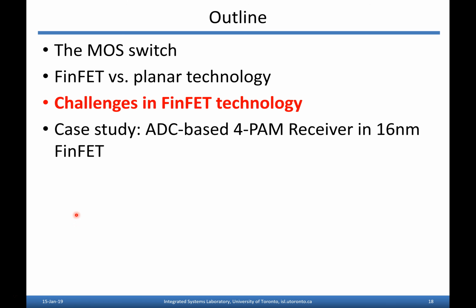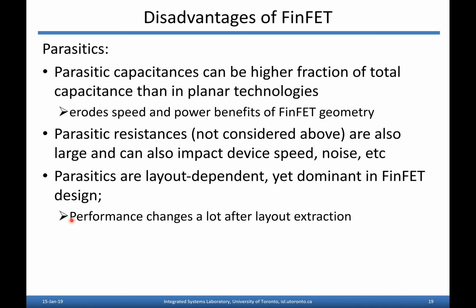So all that sounds great, but there are other really important drawbacks and limitations with FinFETs too. That's what we're going to talk about next. A lot of them come down to the parasitics associated with FinFETs. Effectively, the geometry is so compact now that things are getting closer together and wires are getting narrower, so you've got more capacitance and more resistance as a consequence.